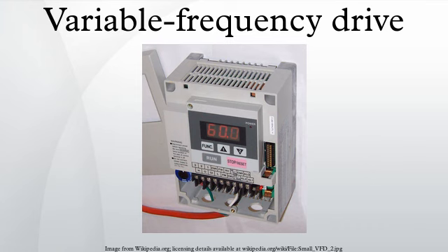Regarding lowering of carrier frequency, note that audible noise is noticeably increased for carrier frequencies less than about 6 kHz and is most noticeable at about 3 kHz. Note also that selection of optimum PWM carrier frequency for AC drives involves balancing noise, heat, motor insulation stress, common mode voltage-induced motor bearing current damage, smooth motor operation, and other factors. Further harmonics attenuation can be obtained by using an LC low-pass sine wave filter, or VFD filter.